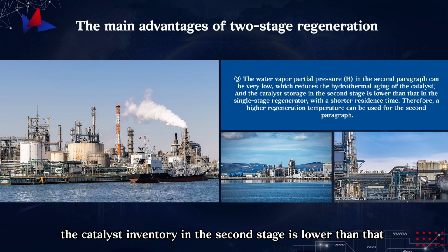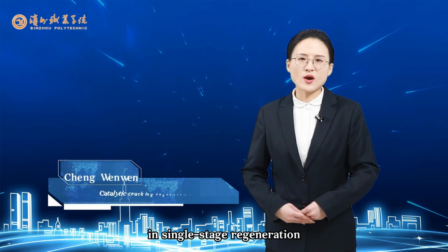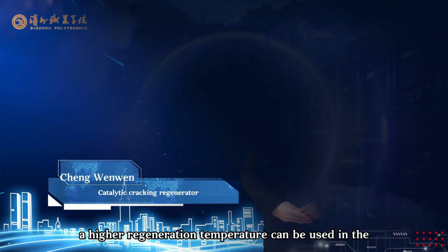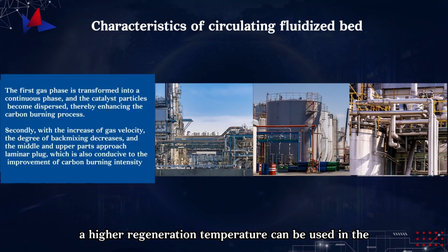Furthermore, the catalyst inventory in the second stage is lower than that in single-stage regeneration, and the residence time is also shorter. Therefore, a higher regeneration temperature can be used in the second stage.